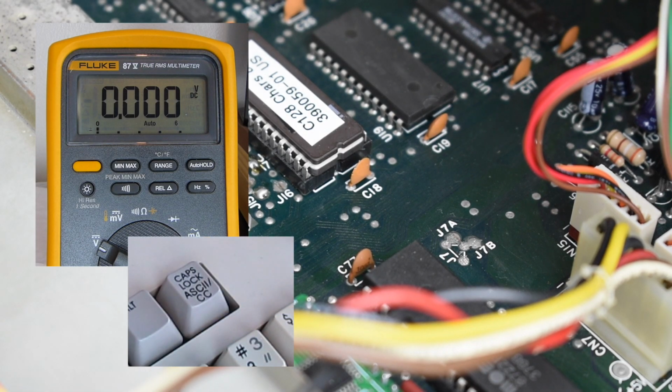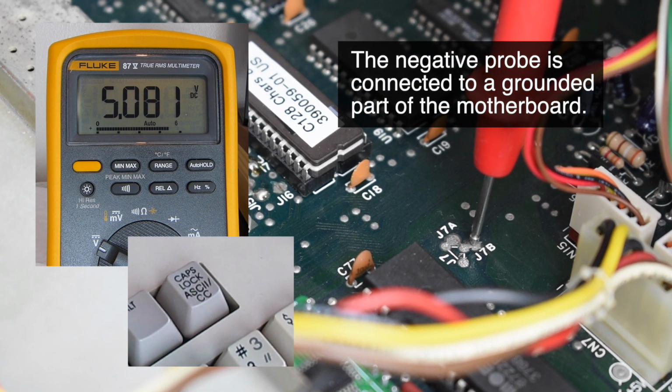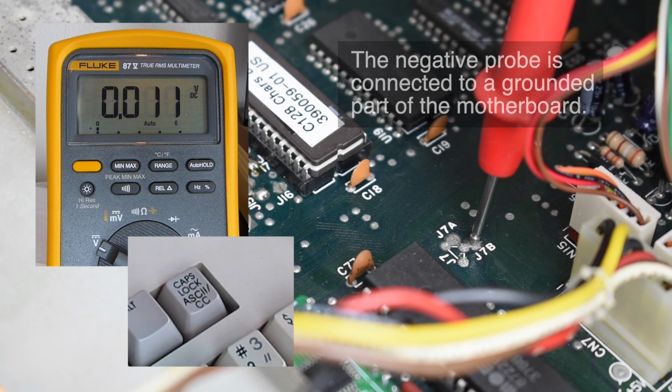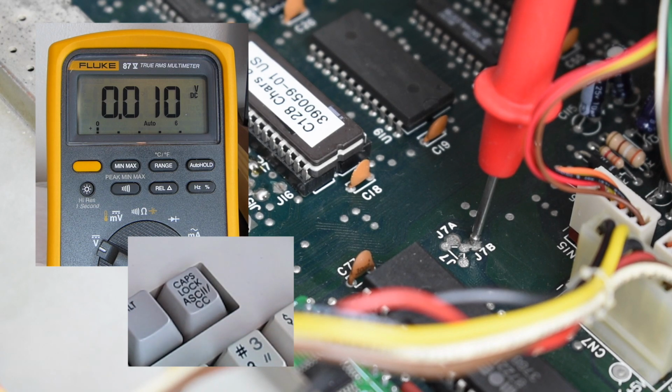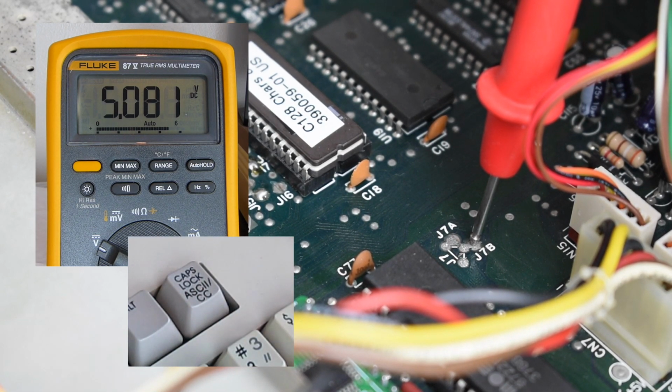Okay, so if I put my probe on the 7B jumper terminal, you can see that the voltmeter is reading 5 volts. Now if I push the caps lock key, you can see it drops down to near 0, and if I release it again, it raises up to 5. So it seems that 7B is connected to the caps lock key like the circuit diagram shows.